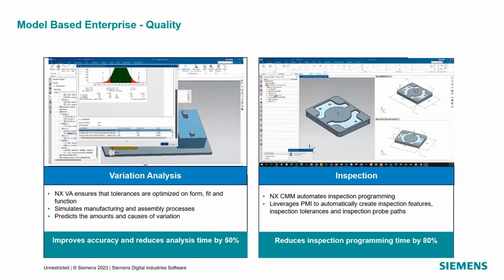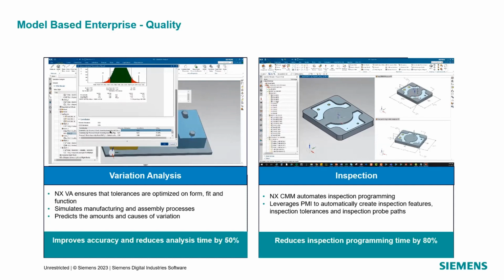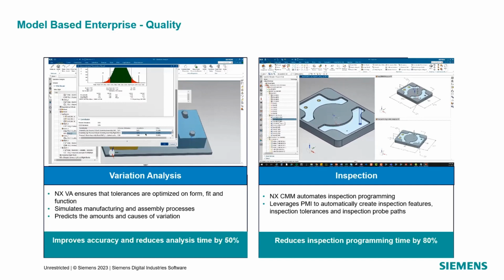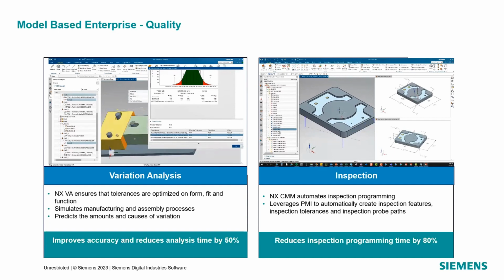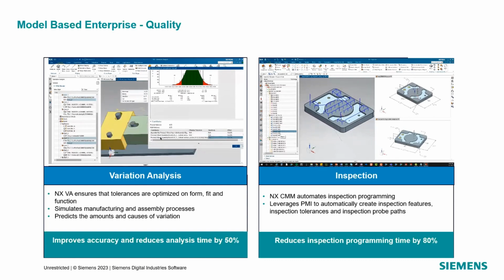It also helps us determine what part we should maybe adjust. Maybe the tolerance is too tight or too loose, and it's causing a manufacturing problem when we assemble it, or we're having issues because of the tolerances that we've put into the design. And so this is a tool to help us improve the accuracy and the build of our products.